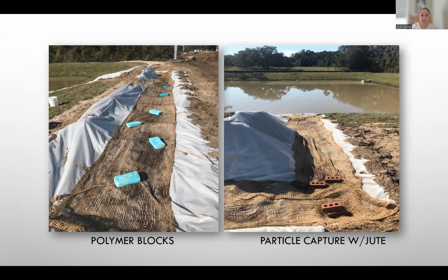We've talked a lot about jute. We can't use enough jute with the flocculants, and put the correct form of the flock log down the channel. You can see the blue logs there in the left picture, and then they have some jute, which also aids with mixing. In many cases, we have to get turbidity below 32, depending on the body we're going to be discharging to.